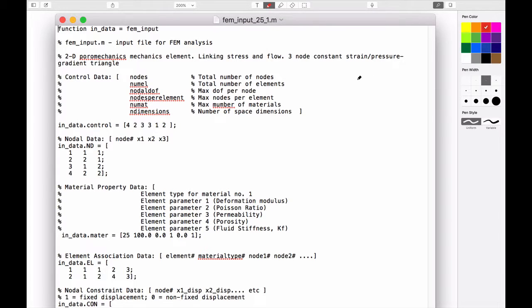That is a triangular element. And as we number things from node 1 to 2 to node 3, we keep up with the prescriptions of what we've said before, is that each of these would have degrees of freedom attached to them, and the same for node number 3 in terms of displacements and pressures.